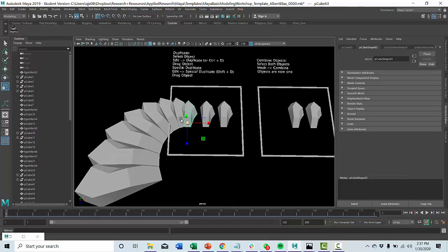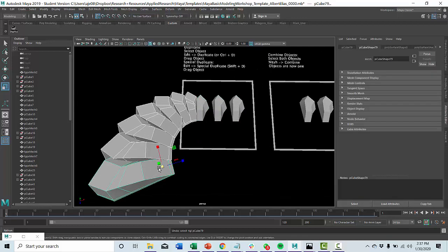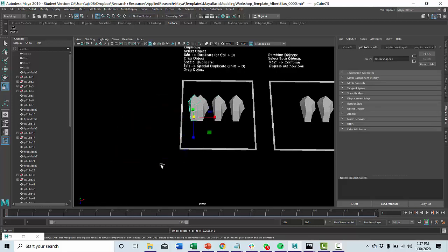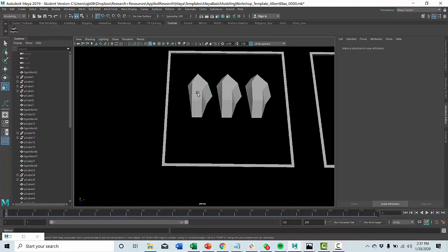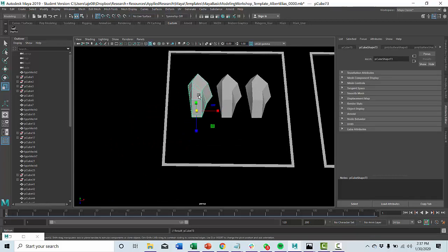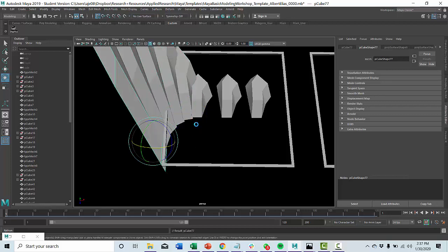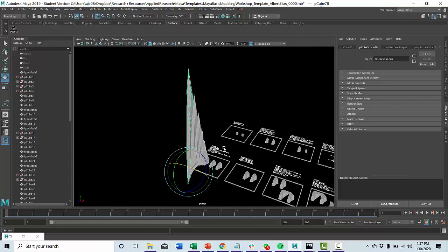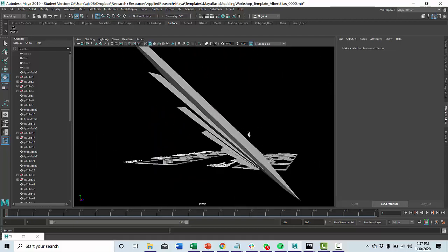So I'll do it again. If you select the object, you're going to hit Shift D. You're going to move it aside. Maybe rotate it. Maybe scale it. Maybe you can see it one direction. Maybe rotate it again. And then just hit Shift D, right? This can really rapidly get heavy, so be careful when you do this.